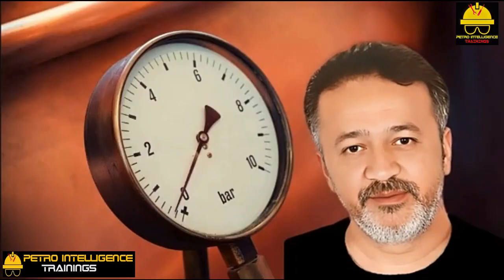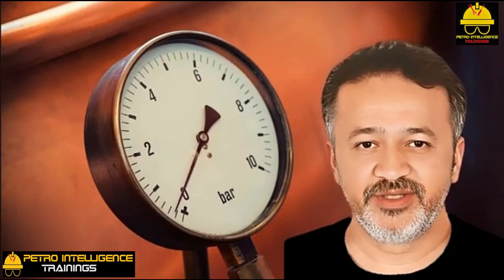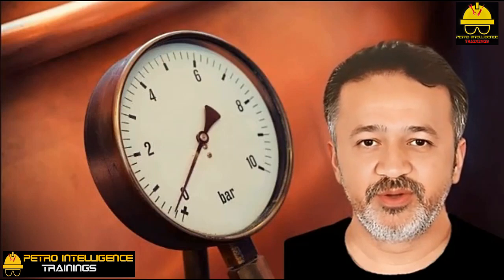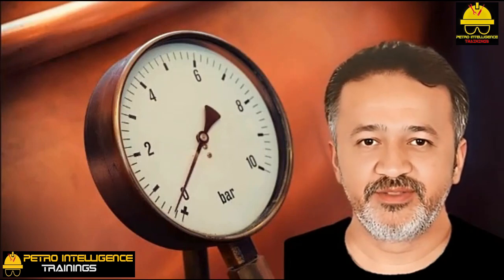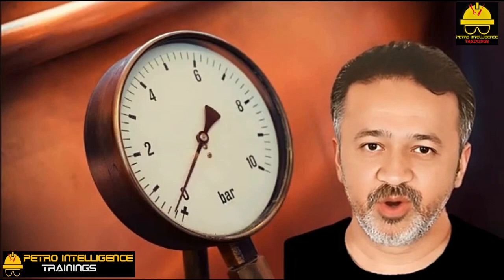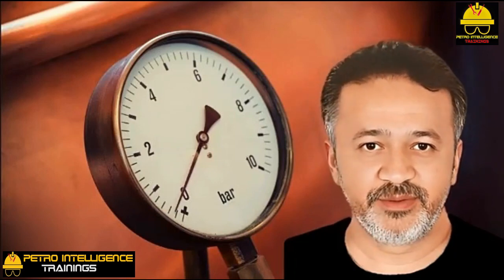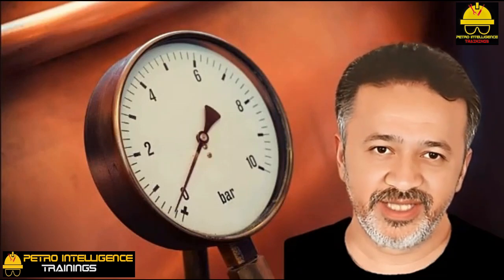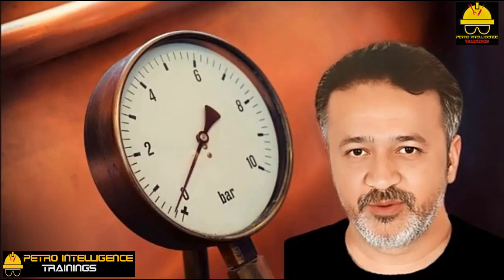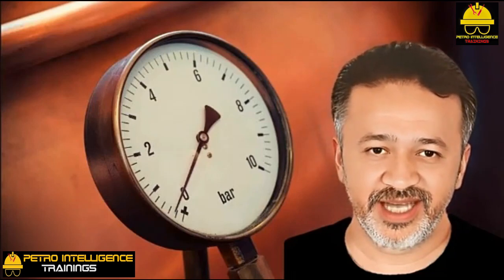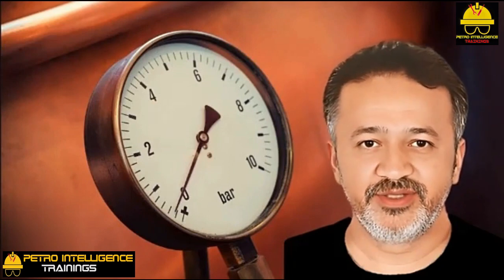Plugged taps. How do plugged level sensing taps affect the apparent liquid level in a vessel? Let's assume that the vapor in the vessel could be fully condensed at the temperature in the gauge glass. If the bottom tap is closed, the level will go up because the condensing vapors cannot drain out of the glass. If the top tap is closed, the level will go up because the condensing vapors create an area of low pressure, which draws the liquid up the glass through the bottom tap. Thus, if either the top or bottom taps plug, the result is a false high-level indication.